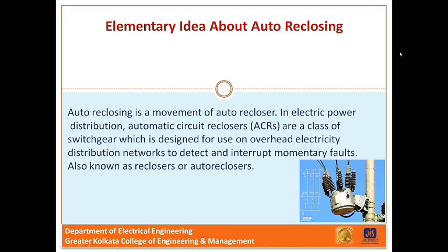Now, modern recloser installations are often equipped with SCADA communication, allowing the majority of reclosers to be remotely operated by staff in the utility room. And this allows for switching the circuit, as operators can use information provided by the reclosers in the field to configure the distribution network if a fault is detected in the field or to fix a load flow issue. Remote control of reclosers also saves significant operational expenditure as it can reduce the necessity of field crews to travel to site to reset devices which have transitioned to lockout.